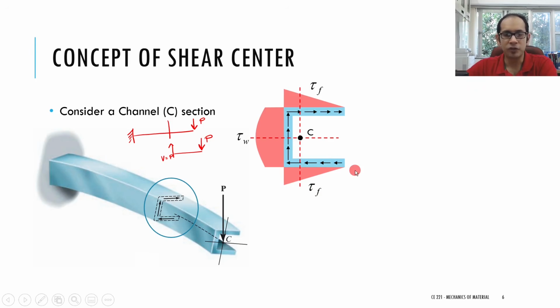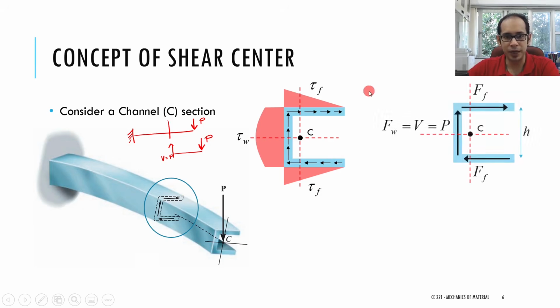So here this is the shear stress. Now from the stress, if I try to get the force, how do I get the force from the stress? Here the force from the stress would be simply, so this is the triangular. So remember, we always try to idealize, and remember one more important thing: these triangles and this parabolic part are only a representation of the magnitude, not the direction. The direction of the shear flow, the shear stress, happens something like this over here. Now from this stress diagram, if I try to get the force diagram, this is how it looks over here.